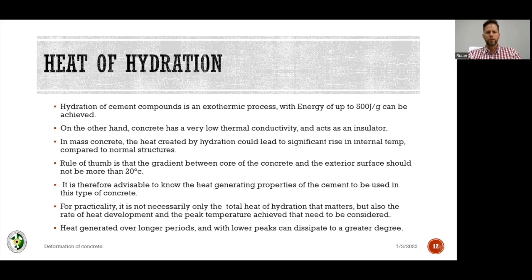And then for shrinkage constraints, the consultants and the client specifically made note of the concrete placement temperature. If the concrete placement temperature is above 30 degrees, the concrete gets rejected. So now this truck pitches up on site, and the temperature was taken at the batch plant, let's say 25 degrees.